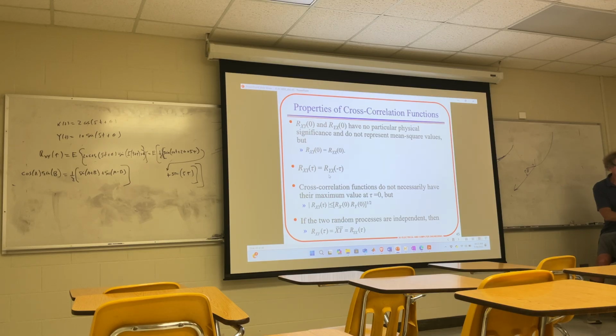Anytime you have a cross-correlation function, it is symmetric, or an even function. Does everybody understand what I mean when I say even? So right off the bat, if you see a cross-correlation function that is not even but odd, you know that's impossible. Or I should say, for the negative values, you know it's impossible.